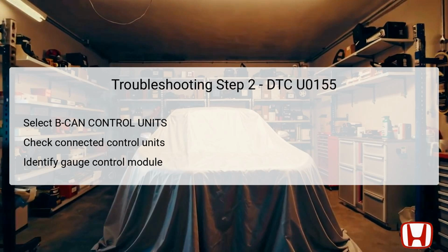It is essential to determine if the gauge control module is detected by the system. If the module is present, this confirms that communication infrastructure is in place and further diagnostics can proceed. However, if it is not detected, this suggests a possible failure in the gauge control module or related communication connections requiring further analysis.